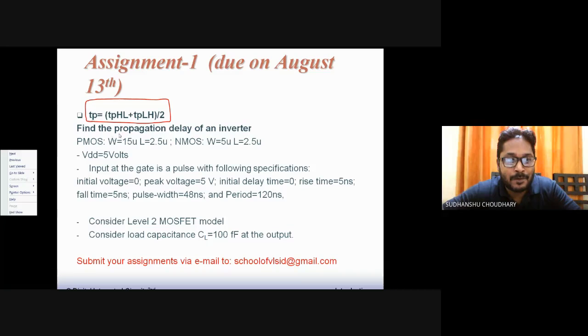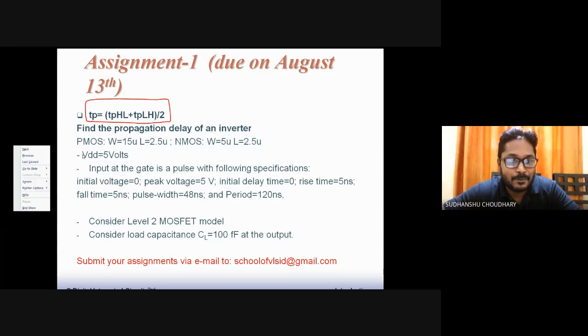Here you have to find the propagation delay of a CMOS inverter that has a PMOS with a width of 15 microns and length of 2.5 microns, and an NMOS with a width of 5 microns and length of 2.5 microns. VDD is 5 volts. These are all given parameters. And the input at the gate is a pulse, and this pulse has the following specifications.